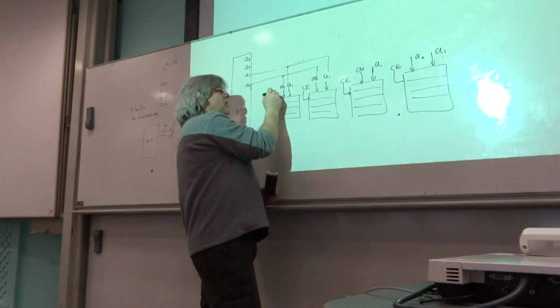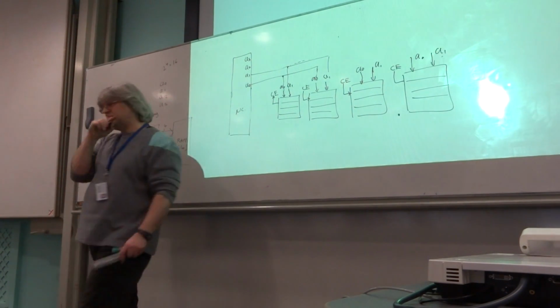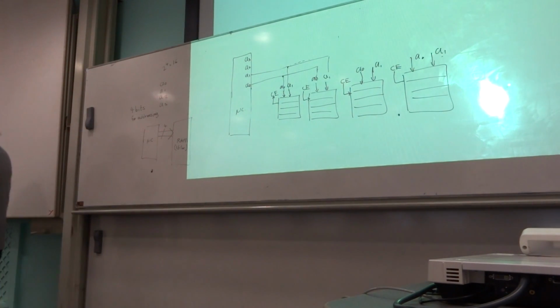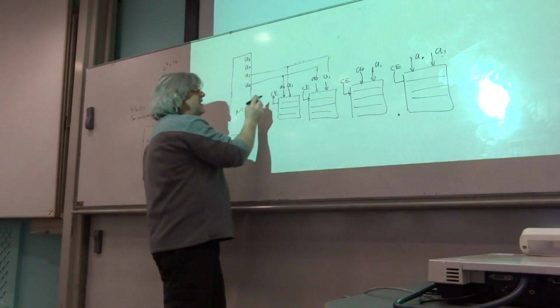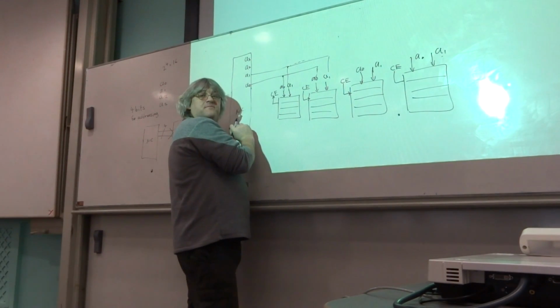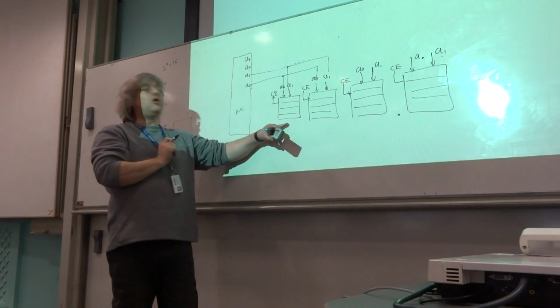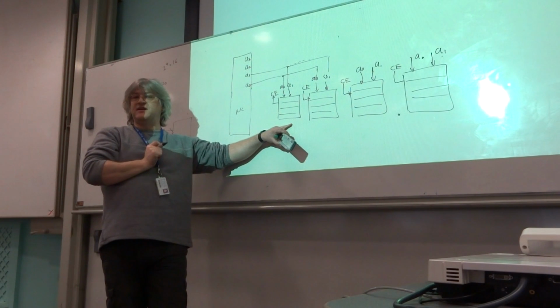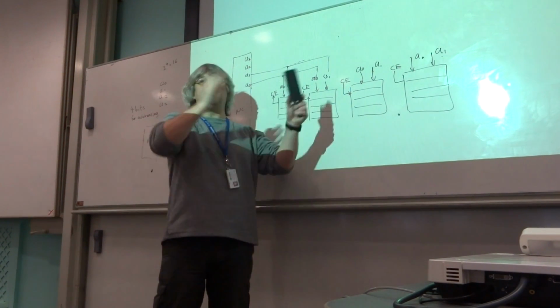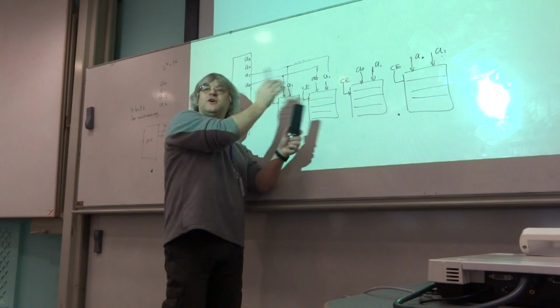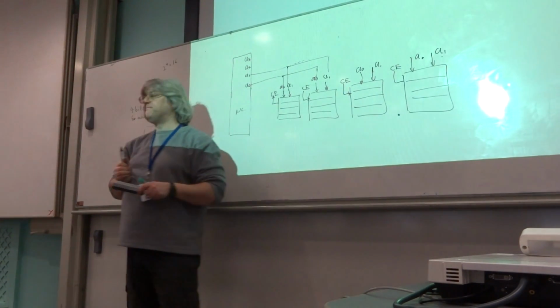And it's very, very common. It's usually only one pin, and if the pin is in one state, now it could be high or low, but the manufacturer will tell you, effectively the whole device goes to sleep and does nothing. And in the other state, the device is awake, and anything you write to it will go into it, and anything you read from it will come out of it. Okay?